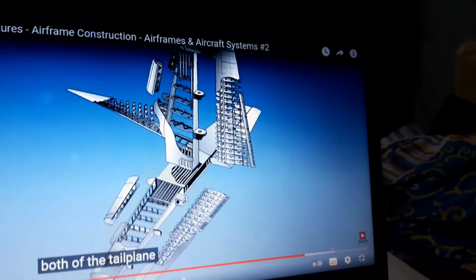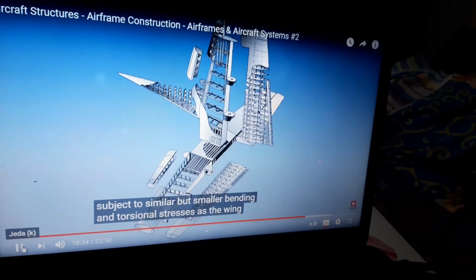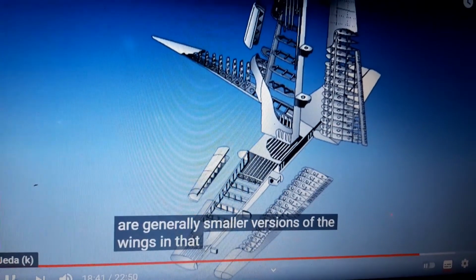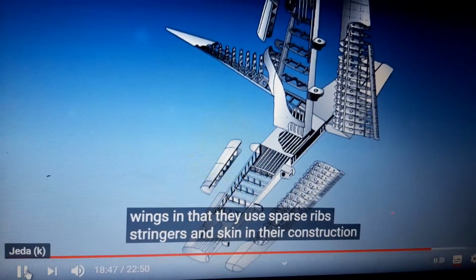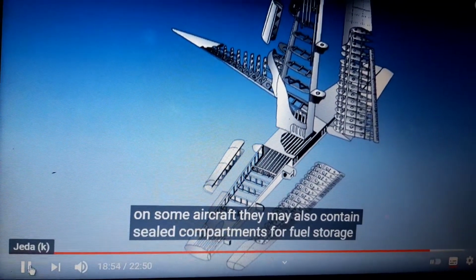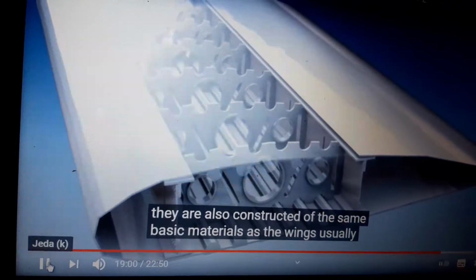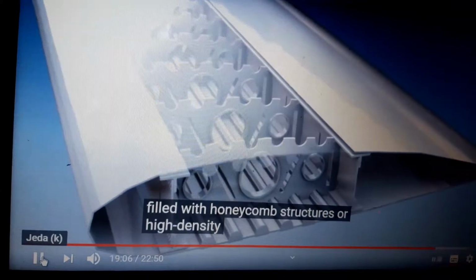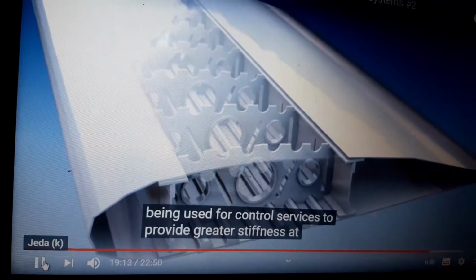Both the tailplane and the fin are subject to similar, but smaller, bending and torsional stresses as the wing. Structurally, the tail unit components are generally smaller versions of the wings, in that they use spars, ribs, stringers, and skin in their construction. On some aircraft, they may also contain sealed compartments for fuel storage. They are also constructed of the same basic materials as the wings. Usually, aluminium alloys are used, with composites filled with honeycomb structures, or high-density expanding foam, sometimes being used for control surfaces to provide greater stiffness at low weight.